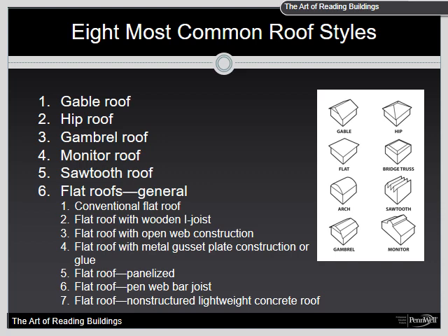This type of construction can last approximately 4 times longer than 2 by 4 pieces of lumber in trusses when they are exposed to fire. The stronger areas of this roof are the ridge and valley, and the areas where the rafters cross the outside walls.